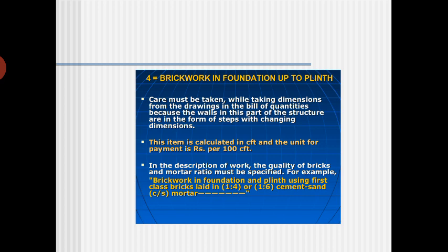And if the brickwork in the foundation and plinth uses first class bricks laid in 1:4 cement and sand mortar, some of the rates they have given, maybe I'll supply them. For 1:4 what will be the rate, for 1:6 what will be the rate, for mosaic floor what will be the rate. This is already there in the SR rate, you have to see the SR rate and do it.